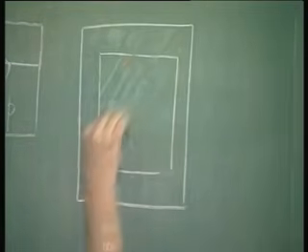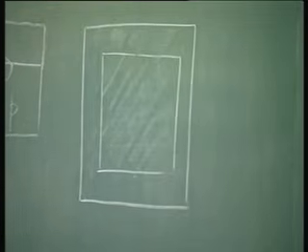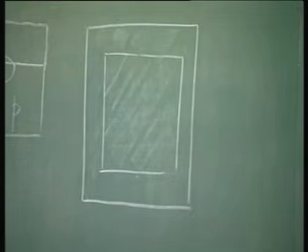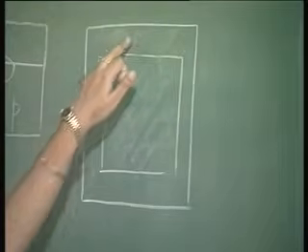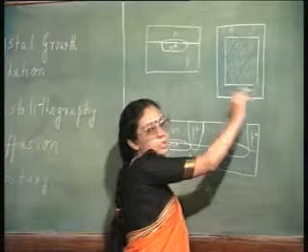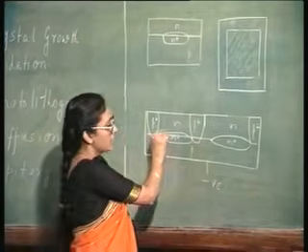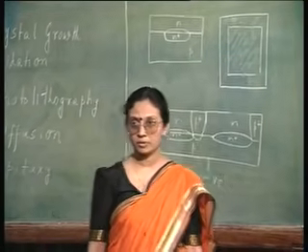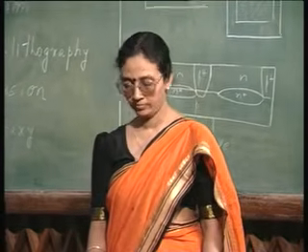Now, this portion becomes dark. I have surrounding the active region the diffusion window for isolation diffusion, that is the P plus dopant can enter only through this region surrounding the active region of your transistor. The active region is marked by this N plus buried layer diffusion, right. Okay.